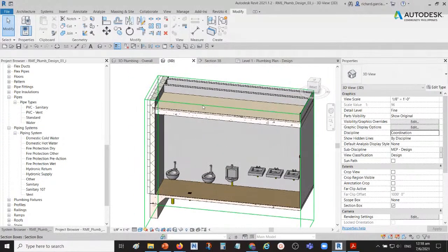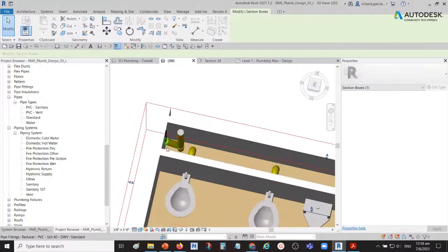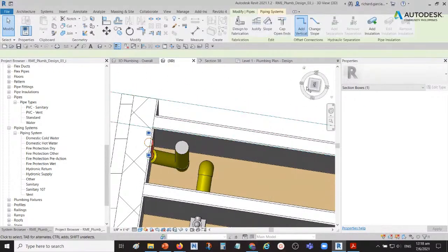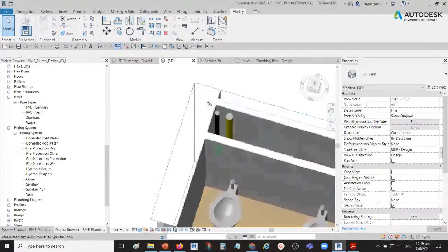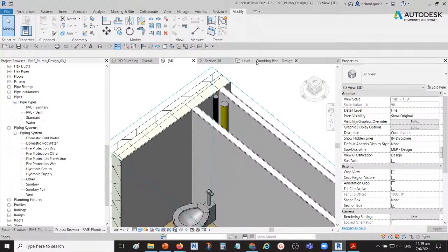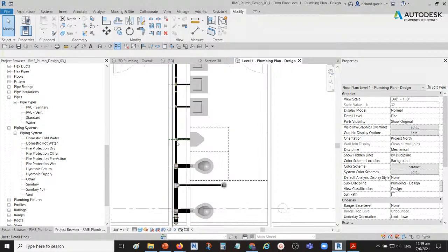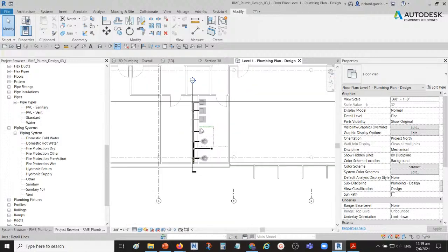So you can use the section box to check and adjust, so just like this one is clashing. Okay, but then again, you also need to know what the stage of the project is. So don't put too much detail if you are just on the developed design. Actually in our company, if it is developed design, we are not connecting too much of our pipe to the main pipe. So what we do is we just create the main pipes and then just put the pipes there.